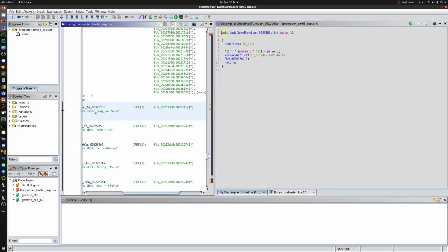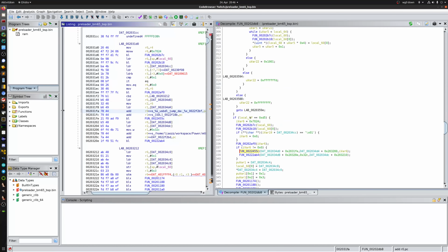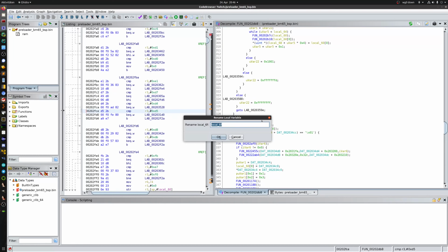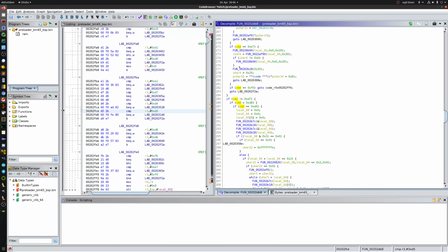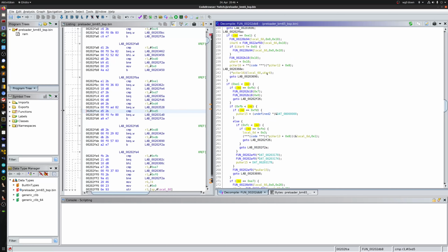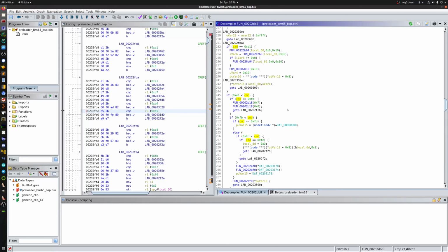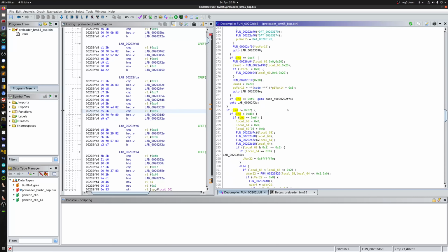That's the easiest thing to find the command handler in the preloader. Just search for USBDL and then go backwards, and then you can see over here that's the command byte which is being used in the preloader, which is also used by SP Flash Tool. So you've got the commands in the Bootrom and you've got the commands in the preloader.